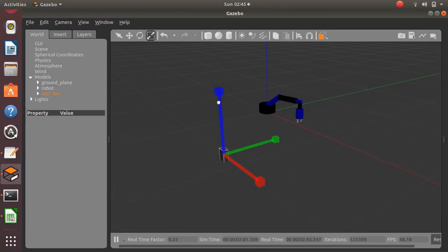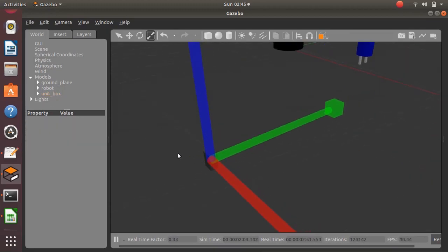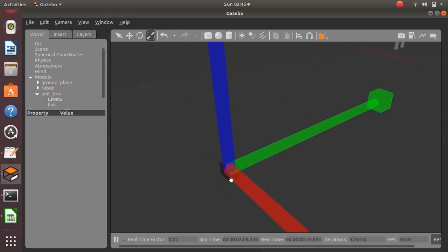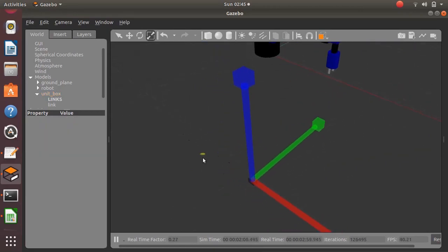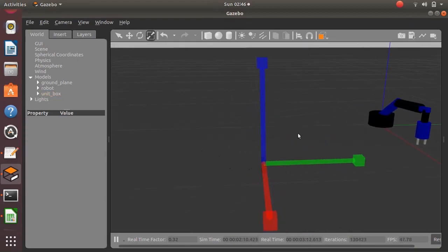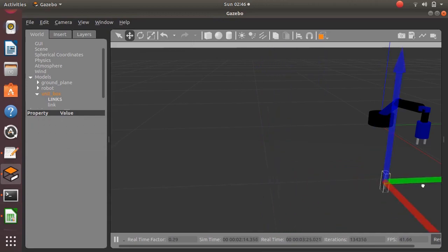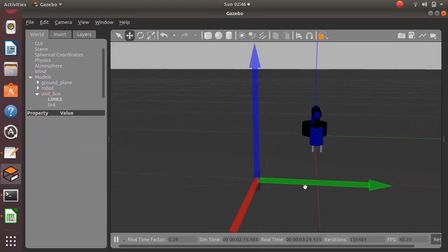place it inside the open gripper so that we will be able to create an object having a relative size of the gripper. After resizing it to a small object that occupies the space inside the gripper, move the object to the open gripper.